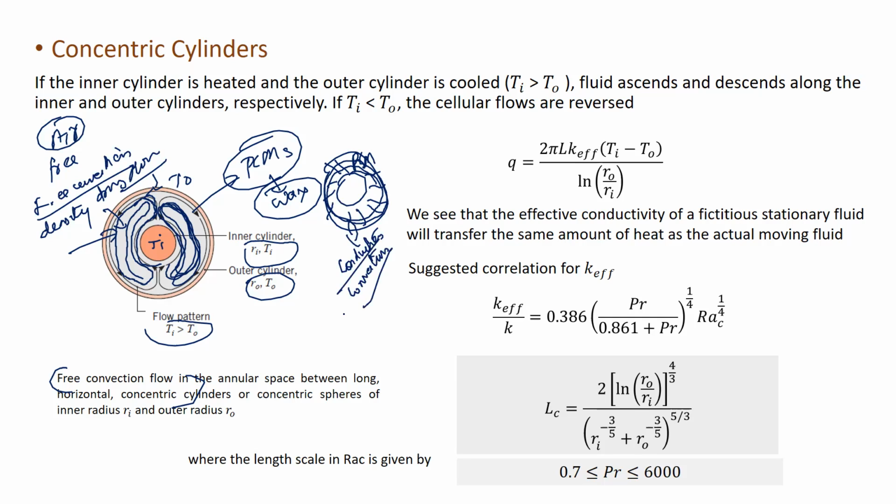Convection will dominate after a lot of time. All the PCM would melt and it would stably settle down. So the initial part will be totally dominated by conduction. In the case of paraffin wax, thermal conductivity is very low, maybe 0.1 or something, but its latent heat is very high.